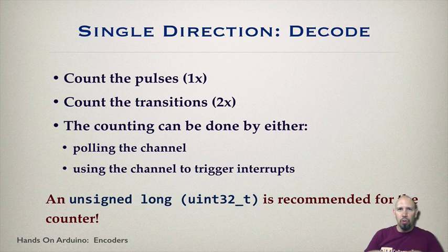When you roll over, it's like your position has increased, and then suddenly it drops down to 0. Not so good, because we know it's not 0. It's actually some large number. It's gone a large number of pulses, and so it's helpful to have a long counter for use with this. So that's simple. We have the two methods, the polling and the interrupt.